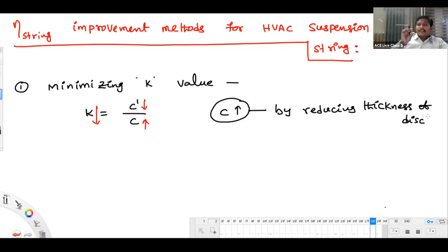or you can say, use higher relative permittivity material. But this option may not be suitable for us. Why is it so? If you are reducing the thickness of the disk, the voltage rating of the disk is definitely going to be reduced. That's the reason.